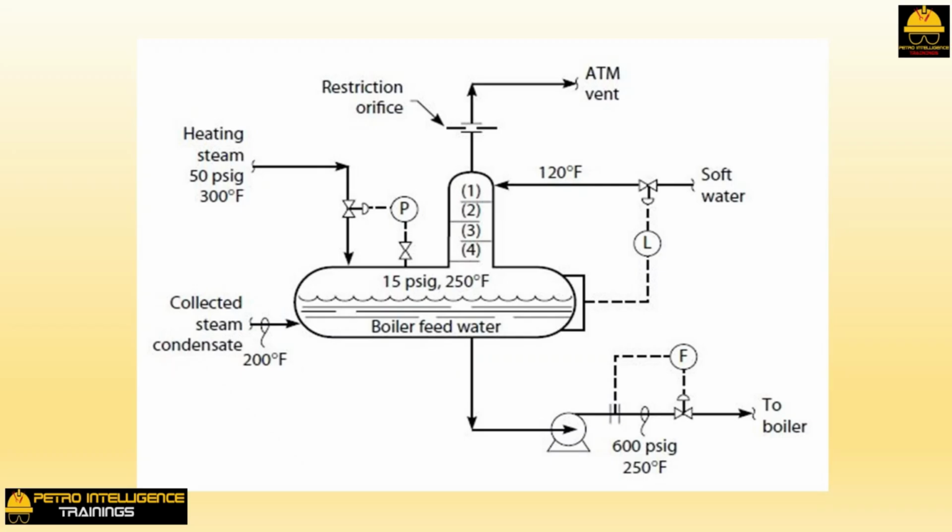The problem was cavitation of the high-pressure boiler feedwater charge pump, as shown in the picture. Such pumps are often multi-stage. This means that there are 3 or 4 pump impellers on a relatively long shaft. The longer the pump shaft, the greater the damage caused by vibration to the pump support bearings and mechanical seal. Cavitation is certainly the leading cause of vibration in centrifugal pump operation. The cause of cavitation in this case was loss of liquid level in the deaerator surge or water storage vessel.